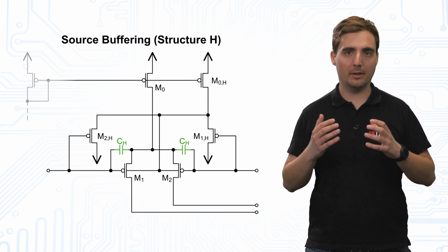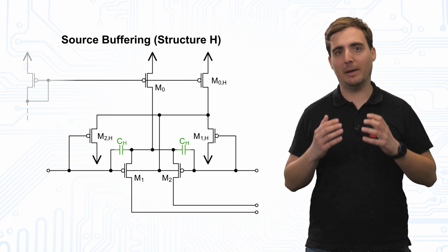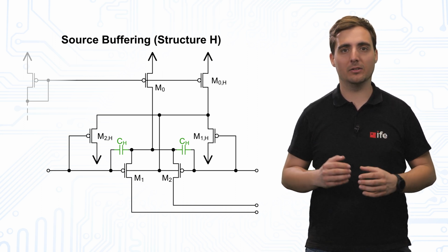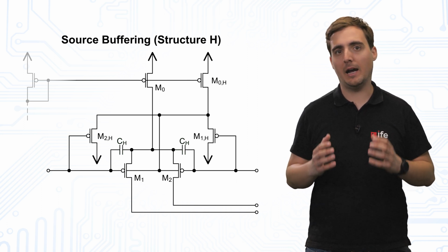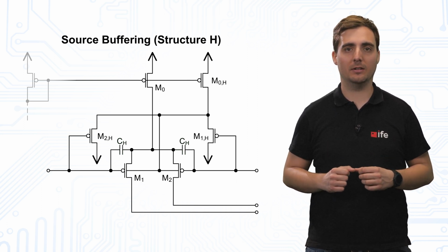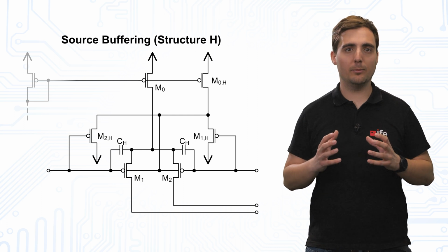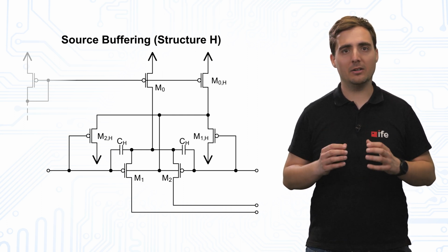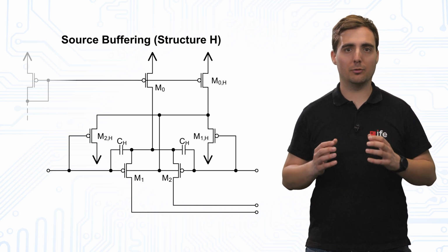The disadvantage with this approach is the need for a capacitance CH that is accurate with regard to absolute values. This is very hard to achieve in integrated circuits. Furthermore, this principle can only be applied for input pair transistors where the bulk terminal is isolated from the substrate.